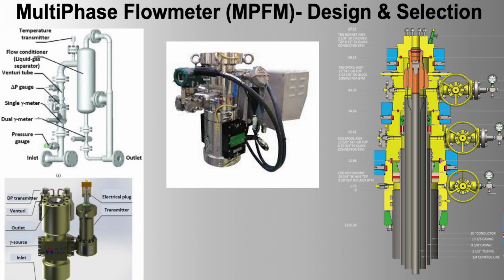2. Enhanced efficiency. Optimized injection rates. Real-time flow data helps in adjusting chemical injection rates dynamically, reducing wastage and ensuring optimal treatment. Cost savings. More accurate dosing and reduced chemical wastage lead to significant cost savings over time. 3. Improved well performance. Prevention of issues. Timely and precise chemical injection helps in preventing common production issues such as scale buildup, corrosion, and emulsions, thereby maintaining well productivity. Increased recovery. Effective chemical treatment can enhance oil recovery rates by maintaining optimal flow conditions within the well.